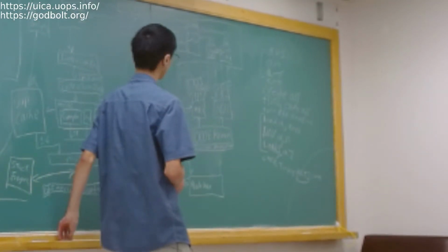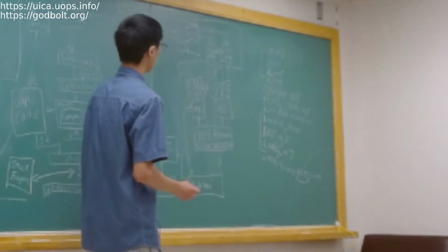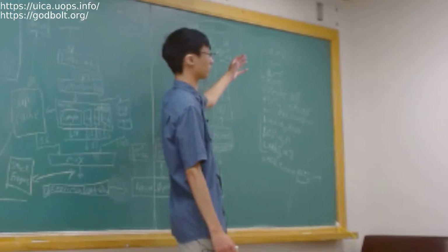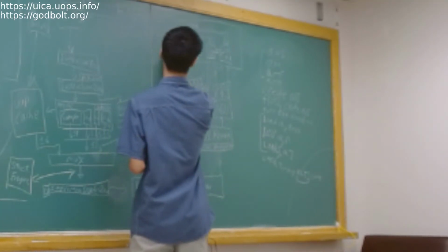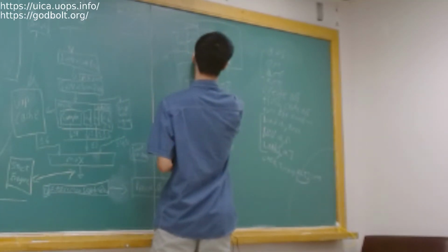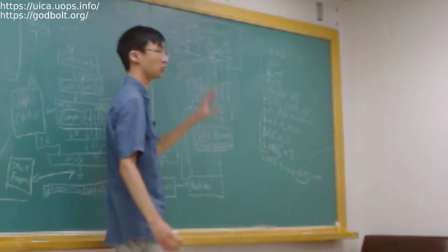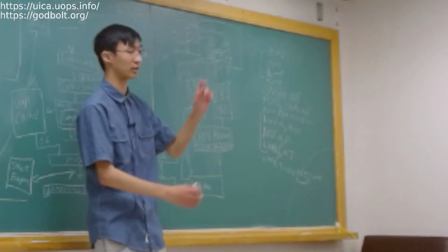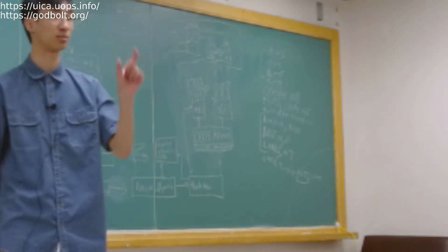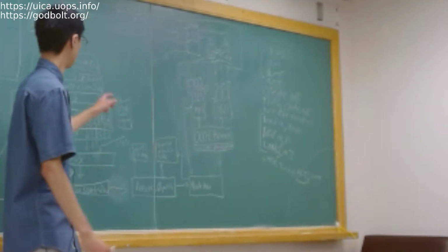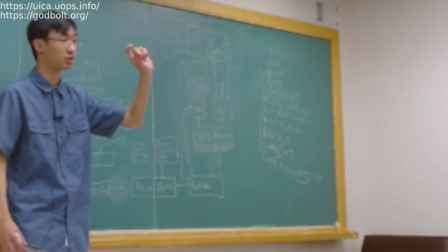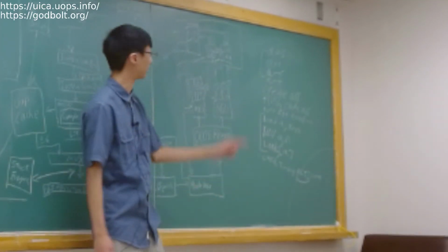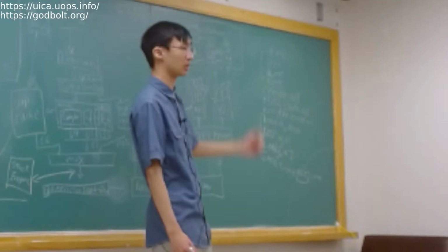And so what we decided was, well, what Intel decided was, okay, well, that sounds bad. Because we can snoop from the line fill and the store and loads, we'll do certain things like we'll zero out these guys, right? If you enter kernel memory or kernel execution, or you exit kernel execution, the OS writers have to write this command called VERW, which we change the microcode sequencer to activate something that will flush these, right? And that way you can't actually start speculating as well.